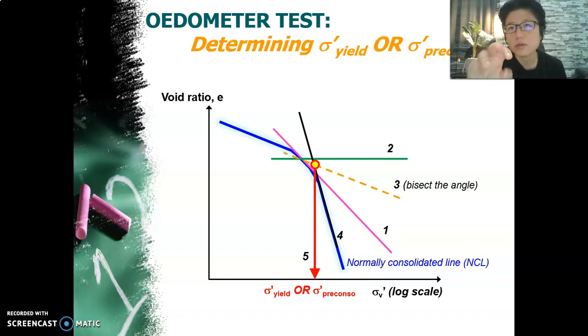This point tells you the maximum stress that the soil has sustained before you took it out from the ground. Alright? So sometimes we say I took the soil from 5 meters down, so on top of it there are 5 meters equivalent of soil weight, correct? If the soil's gamma is 20, then 5 times 20 is 100. But I get this value as, say, 200. So where is the extra 100 coming from? As we discussed earlier, maybe the ground in the area was in the ocean before this, so there was water pressure over it. Or maybe previously, during the ice age, there was a glacier of ice on top of it. All these previous loads on the soil will leave an imprint on it. In other words, your soil will actually have a memory.